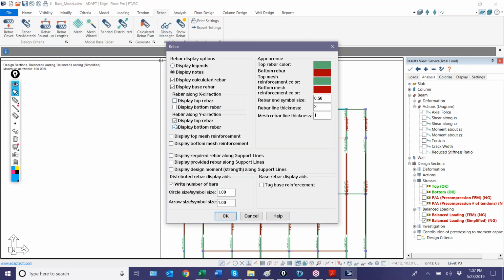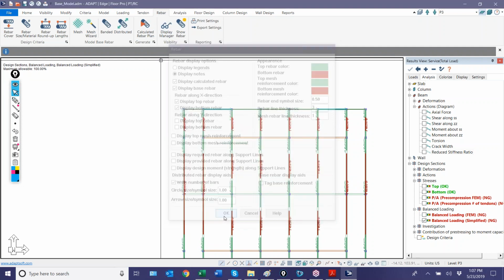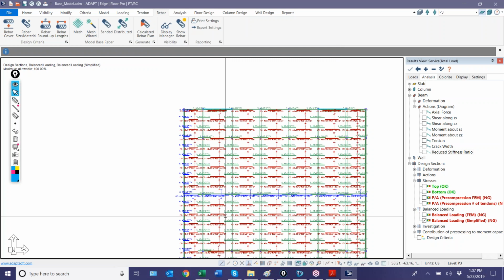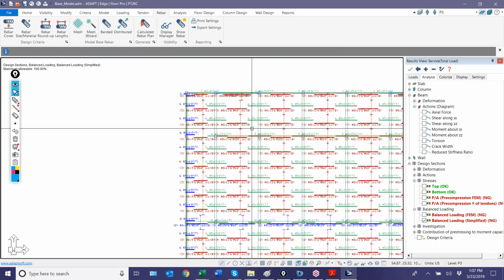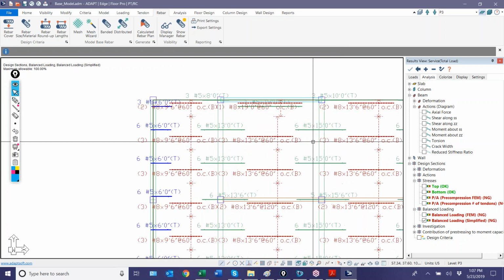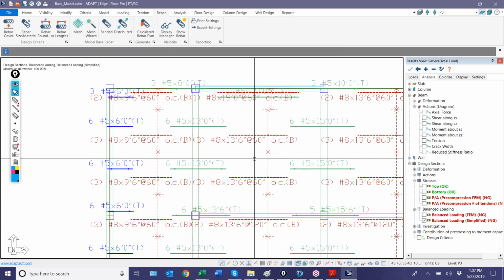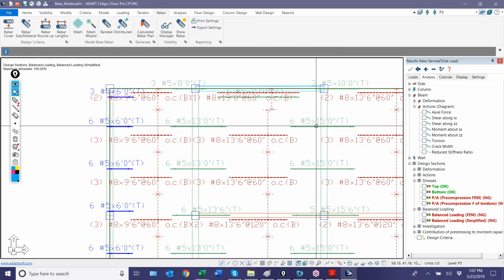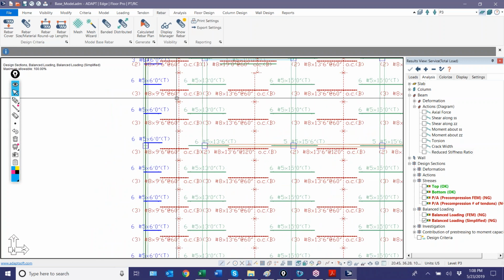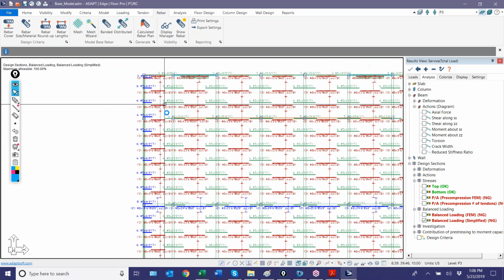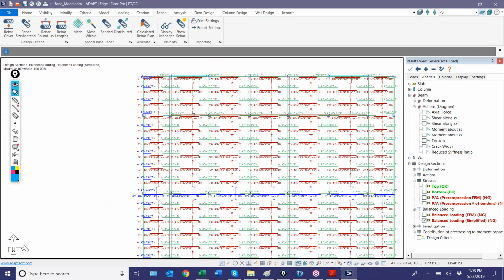If we look at the other direction, which are all one-way slabs, we have something that looks like this. Everything is actually distributed except for the top rebar. The bottom rebar is distributed, top rebar is still grouped in this case. You also have this green again is top, red is bottom, and then you have blue. And you say, well, what is the blue rebar?